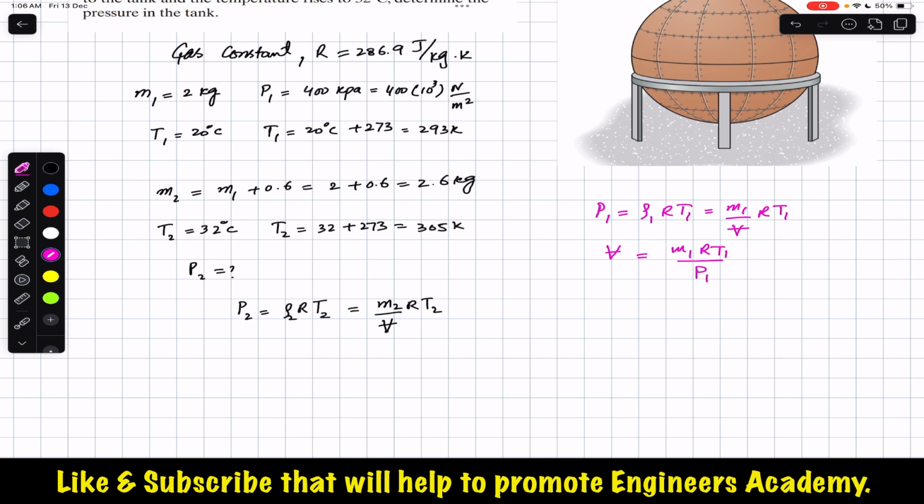So just putting all the values, V volume of the tank is the mass M1, which is 2 kgs, R is 286.9 joule per kg Kelvin into T1. So T1 is 293 Kelvin divided by P1. P1 is 400 into 10 raised to power 3 Newton per meter square.